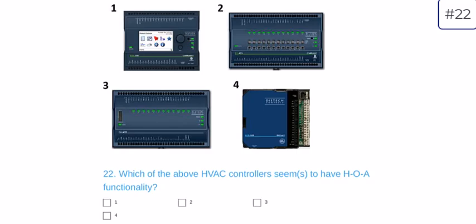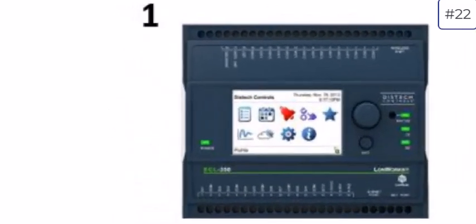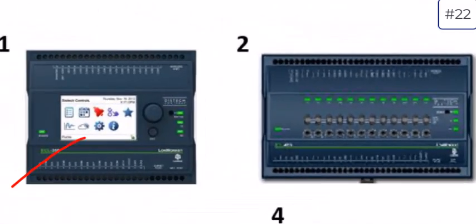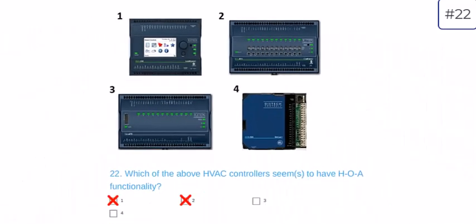However, it can be very handy for functional testing to have something like controller 1 or controller 2, where you have either a digital interface or toggle switches that allow you to override the output, whether it's binary or analog. And typically there might be a screw that you can change on that Model 2 with the toggle switches to change the output to whatever extent on something like a 0 to 10 volt range that has been provided. But these are important as we specify control systems, as we assess systems in the field, to think about the functional test needs and how we can accomplish those.